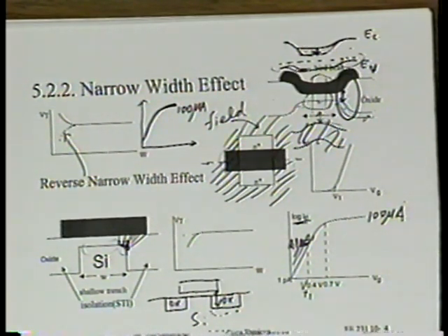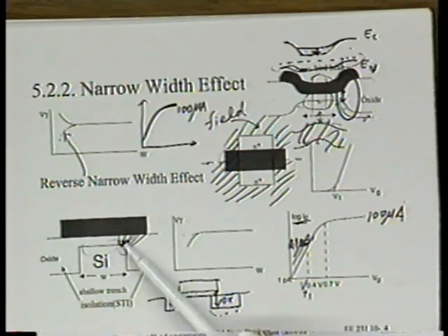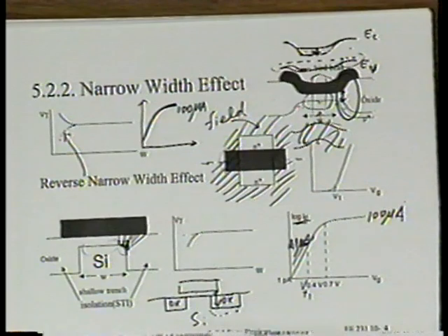Well, I think you know the answer now. When you make the corner smoother, you have minimized this field concentration effect. That's why VT is no longer falling rapidly. But many people miss that point. They just think that because we eliminate the oxide thinning, that's what's responsible for the VT falling. The fact is that between 25 angstrom of oxide and 22 angstrom of oxide, you won't see any difference in the VT. That's a very small difference.